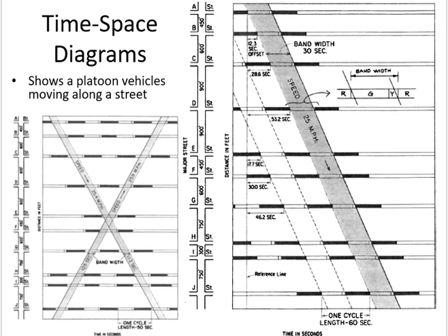When the first major street comes, you will break the coordination. For example, I have this intersection which has a major street, so coordination will be up till here. I will not coordinate this one. Got it? So, main highway, close signals, and crossing minor streets.